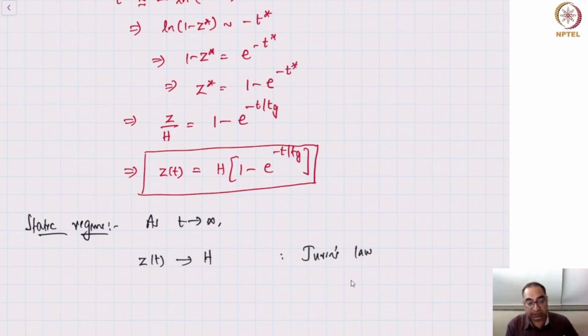So what we have done in these two lectures is we have started with a simple problem of capillary rise in a tube. We have taken all the dominant forces into account: surface tension, gravity, added mass, dynamic pressure, and viscous terms. We've constructed a simple model for the fluid rising in a capillary tube, and then we've derived a nonlinear equation for the height, and we've analyzed this equation in different regimes. Okay, if one has to get the full evolution of the height of the column, one has to solve it numerically. Okay, which is clearly beyond the scope of a lecture like this.